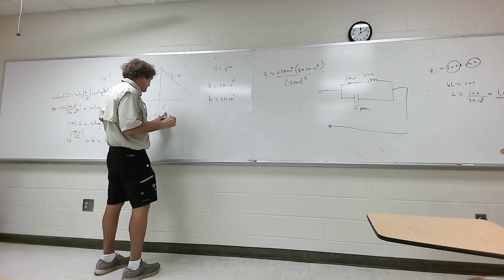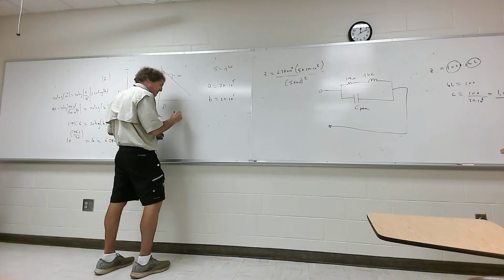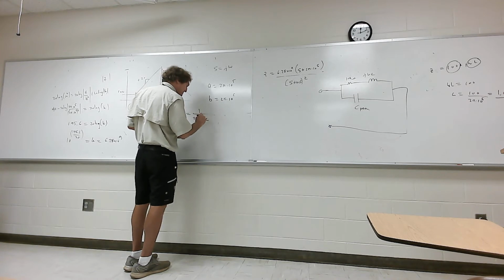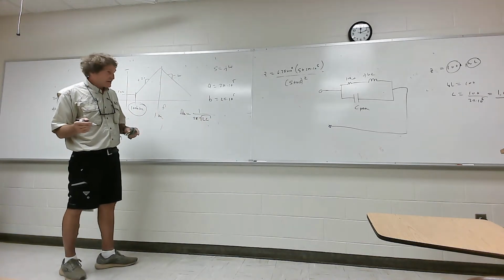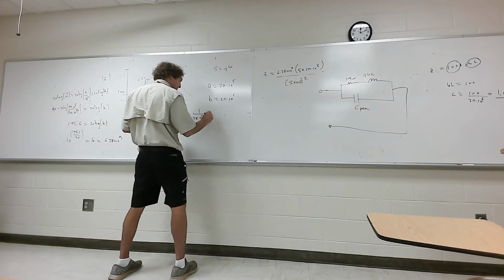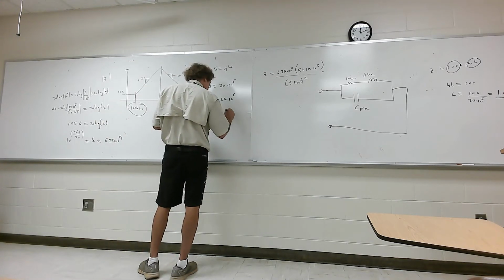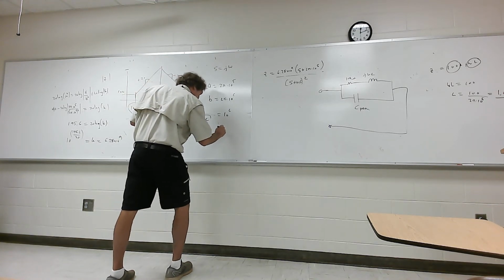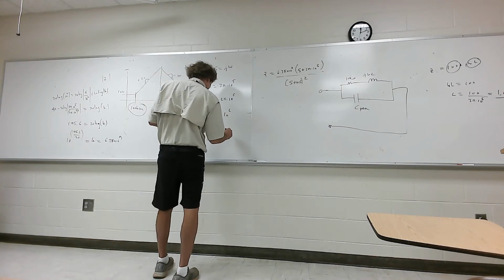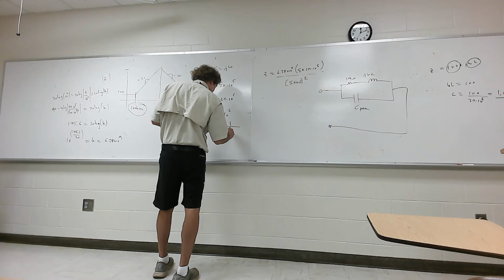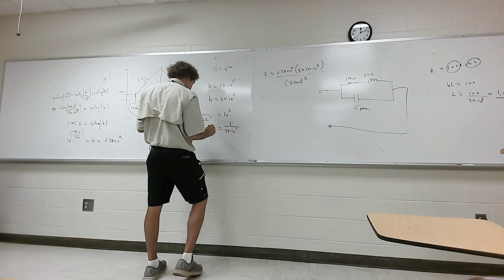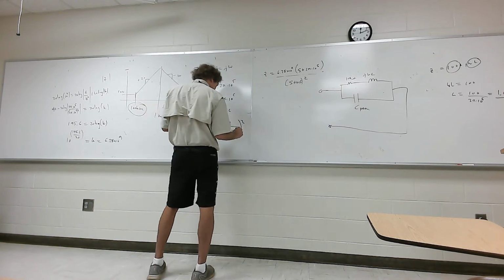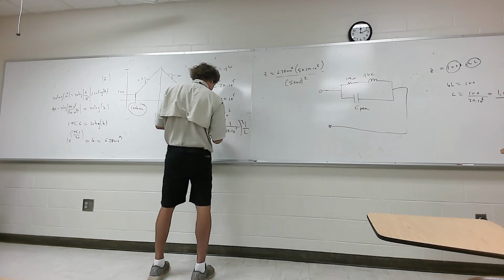This frequency is a self-resonance, so if we think about this, F self-resonance is equal to 1 over 2 pi square root of LC. That's got to be right. If that's L, and this is 10 to the 6th here, then I take 2 pi times that, and then 1 over that, so I have 1 over 2 pi times 10 to the 6th, and that's equal to square root of LC. So I take that and square it, that's equal to LC. If I divide this by L, I get C.